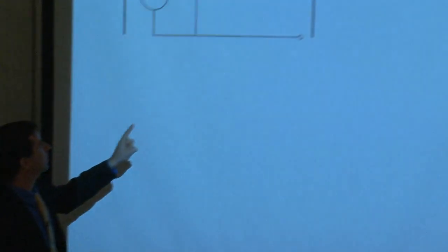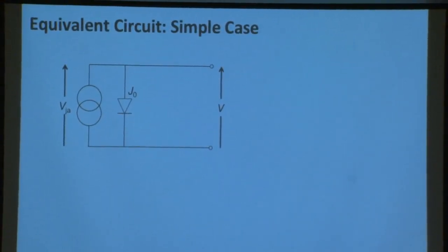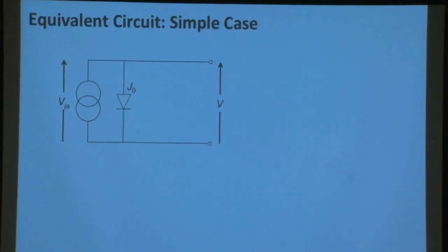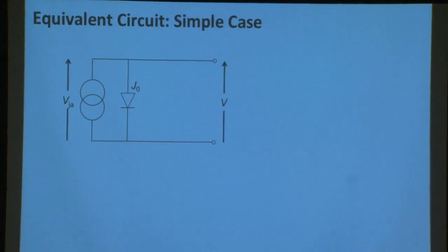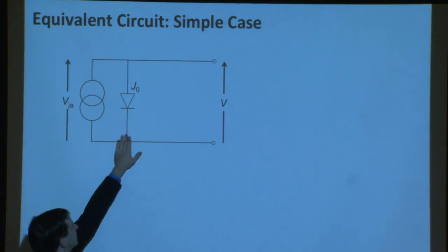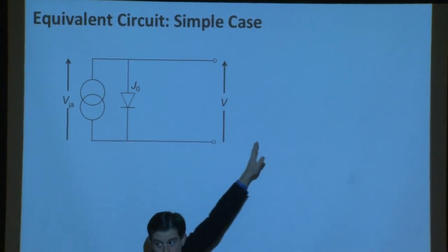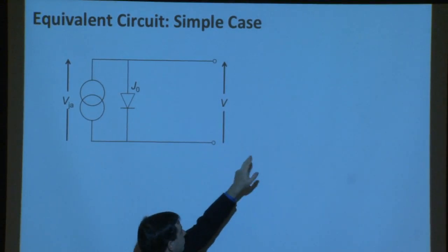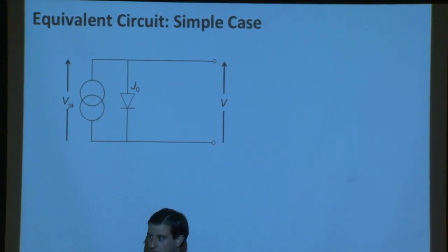So we'll start out with an equivalent circuit diagram of a solar cell device. And this might be new to some folks, but it's all stuff you've seen so far. What we have over here is the current generation source, the solar cell operating under forward bias conditions, under illumination, generating a voltage and a current. We have a diode here that prevents the backflow of current and forces the current to go out through the external circuit loop, right? And it forces it to drive the external load, which would be attached to that little circle over there and that other little circle over there. So you can imagine an external circuit attaching itself right there.